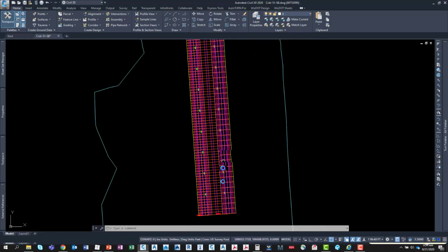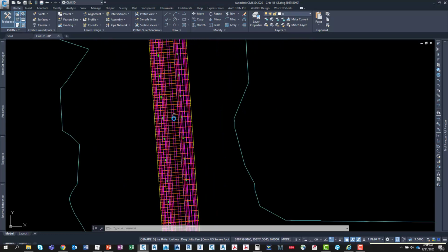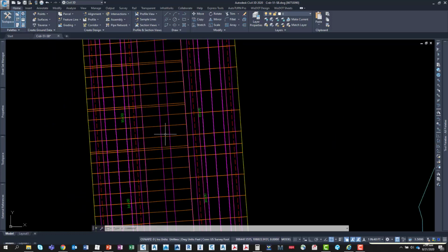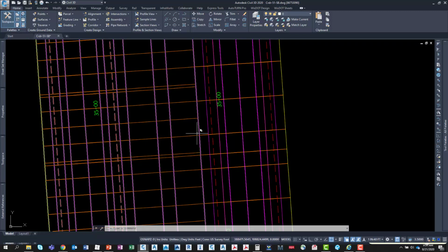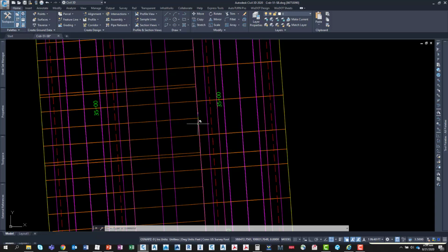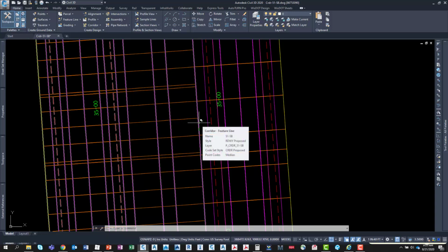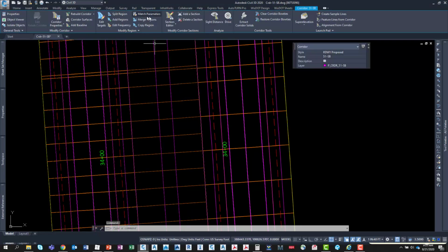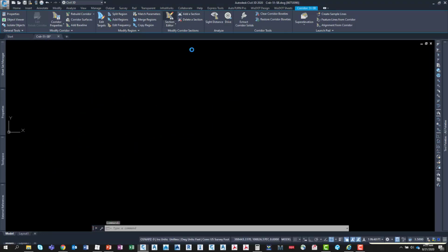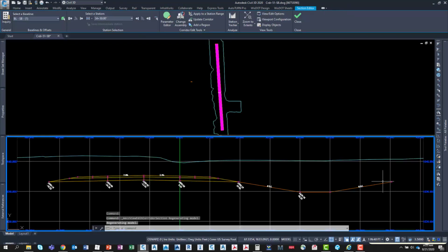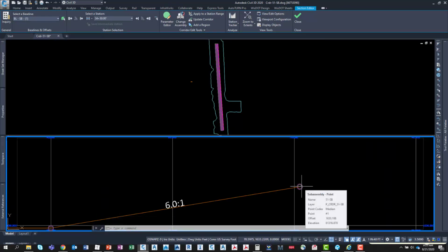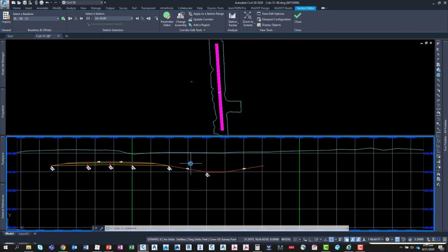It took a little bit to be built because I set the 12.5 feet, which 25 probably would have been okay, but as you can see, the ditch was connected right to that daylight sub feature line on this end. I don't know if we're going to be able to see the other corridor. If there was a surface there, maybe we would be able to, but we'll do a section editor anyways on that frequency. Yeah, it doesn't show it, but you can see it work.